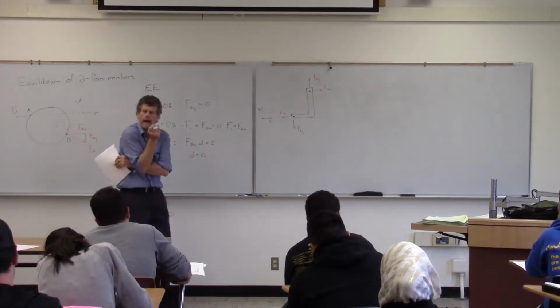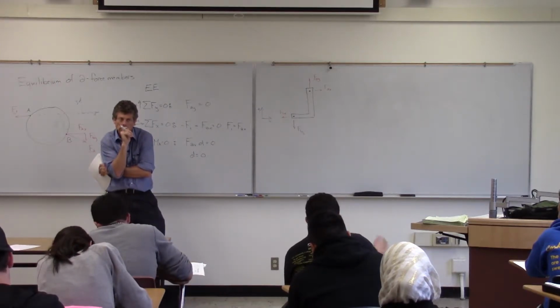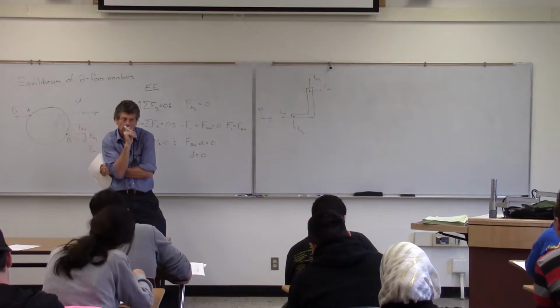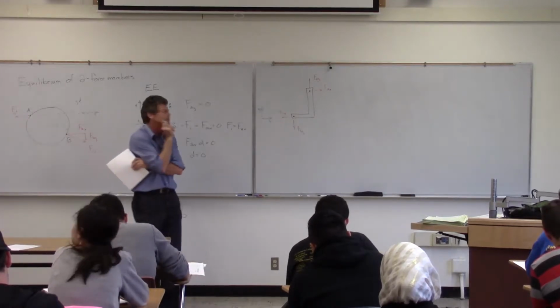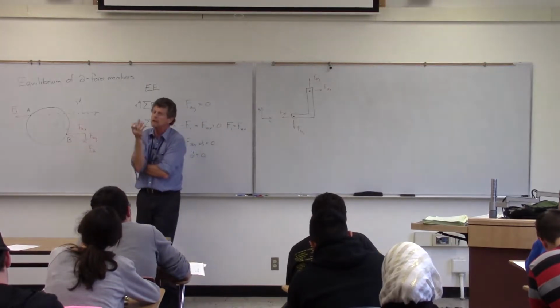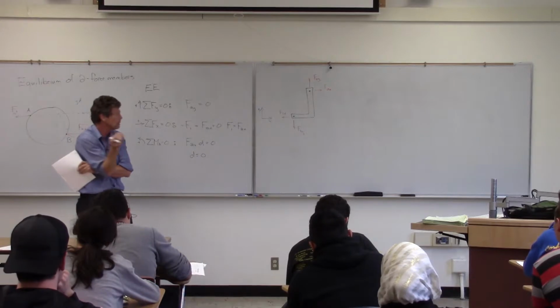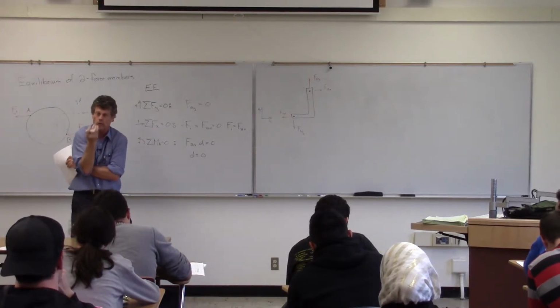How many forces are acting on that member? Two. That's the word you had. You're getting there. It's two forces. Again, there are two unknown components of that force, magnitude and direction, but it's still a two-force member.